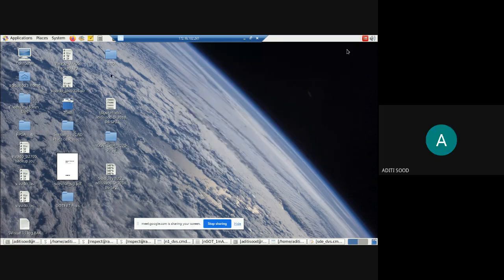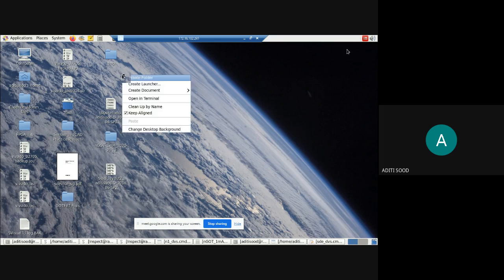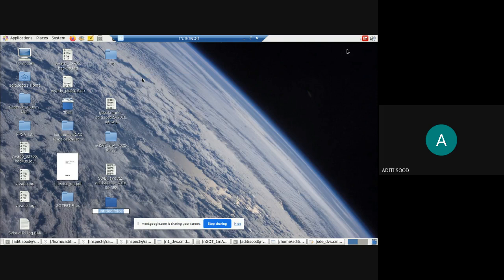So I gather it's the first time that you all are using this tool. This tool has various components. The first one is going to be Sentaurus Device Editor, SDE. For opening that, first of all, we need to create a folder from which we will launch this particular tool. Let's name this folder according to what we are doing today.